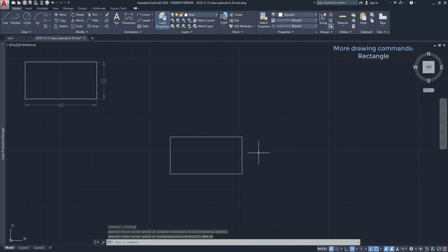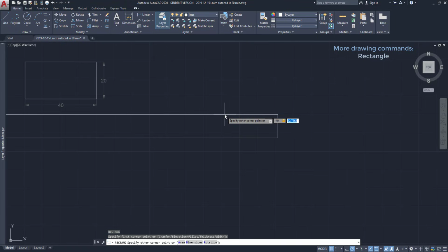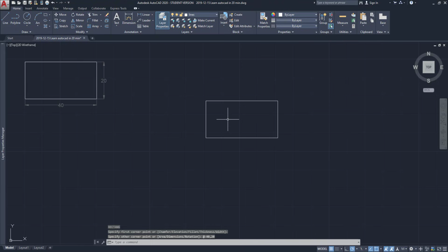However, as I still have to take into consideration the UCS coordinates, sometimes the values might be negative. Let's suppose I draw another rectangle but with the start point x coordinates being -40. Click for the start point, then type -40, press Tab, and as the y coordinates are positive, I type 20. Here you have the result.